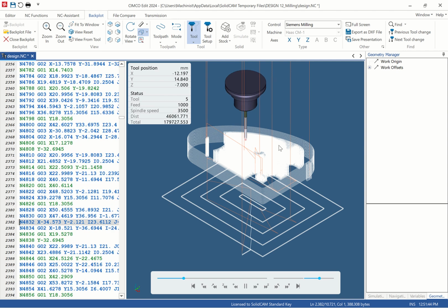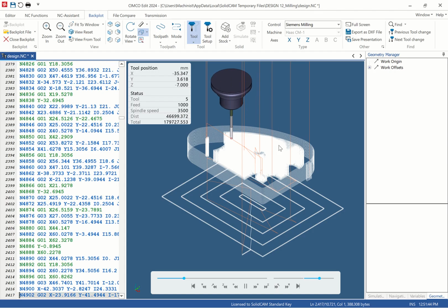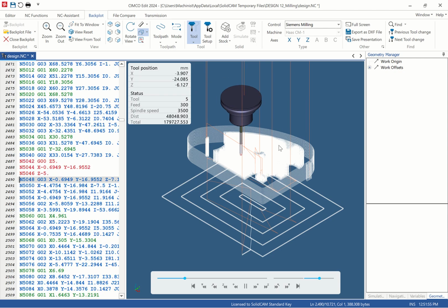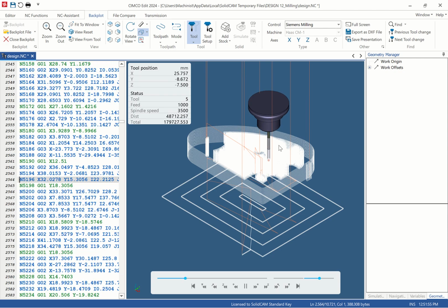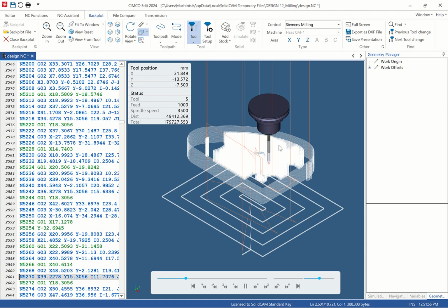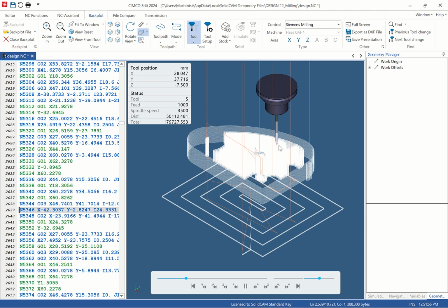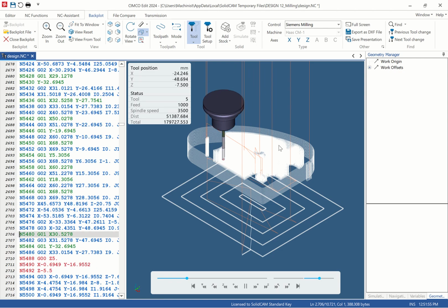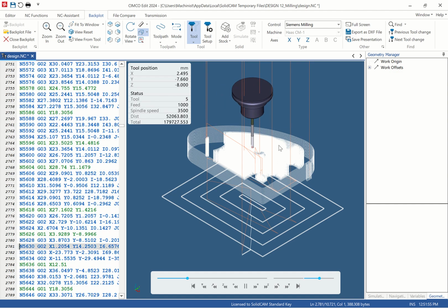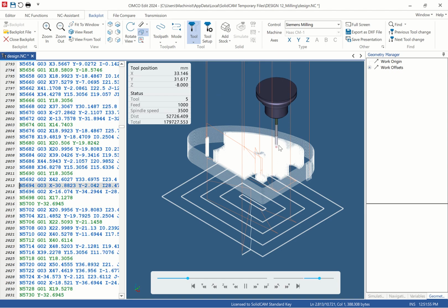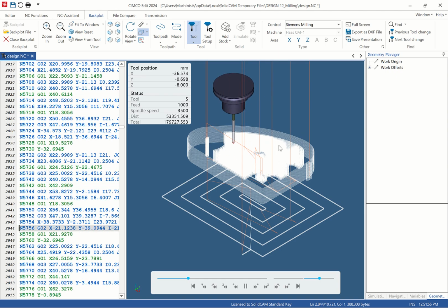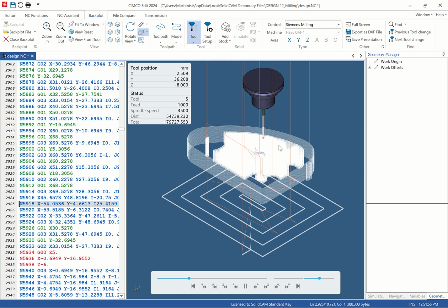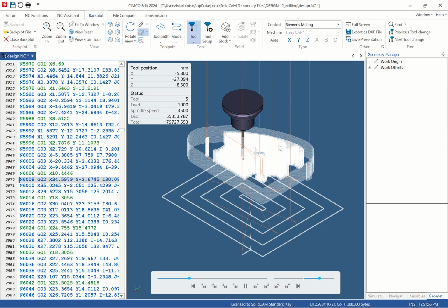So you can check all those parameters because you are dealing with a machine which is very expensive. The tool is very expensive. If you miss one, you have affected the output. You have delayed the client. You have affected the machine. You have affected the tools, and you need to buy more tools. You need to buy material, and you need to buy time so the client can be satisfied with the time limit you have given. So when you're programming, you take time, you take caution, so that you don't break the tool, you don't break the workpiece, and you don't injure the operator next to you, or injure anyone, or endanger somebody around the workshop. So programming is key, but safety is important.